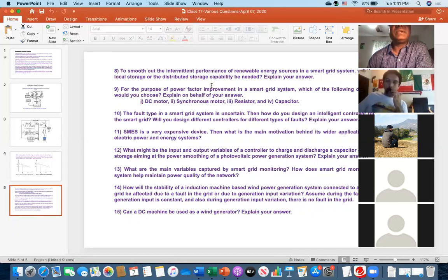So when we are talking about the storage, like battery energy storage, not just the battery. You will be assuming that in addition to that battery, or whatever it is, supercapacitor or SMES system, in addition to that battery or coil or capacitor, there is a DC to DC converter, there is a DC link, there is a voltage source converter.